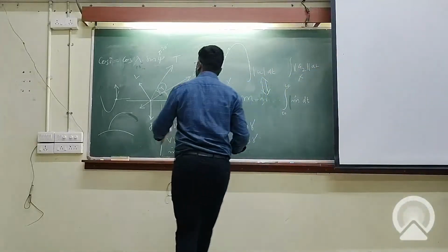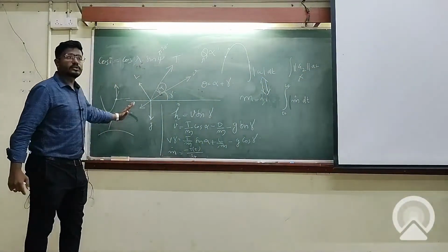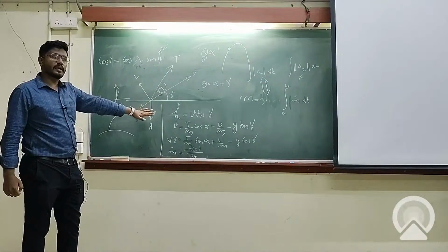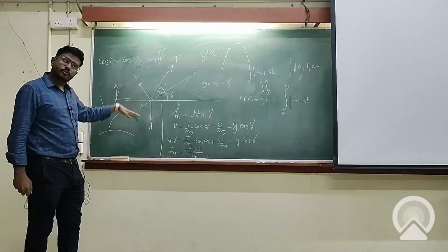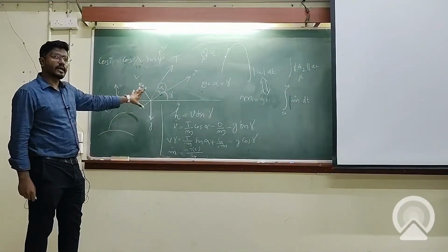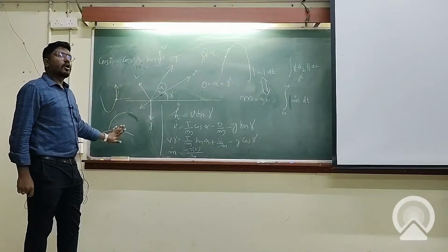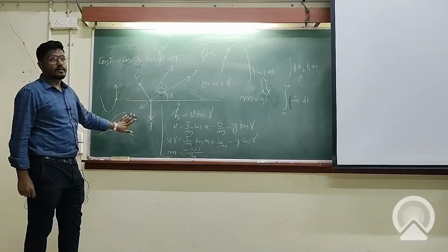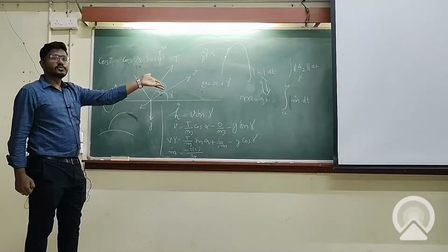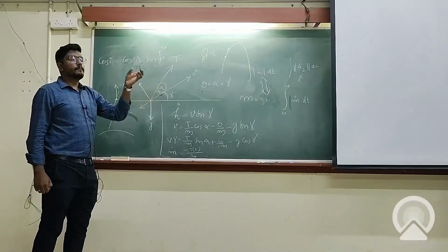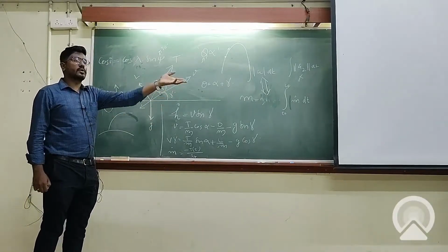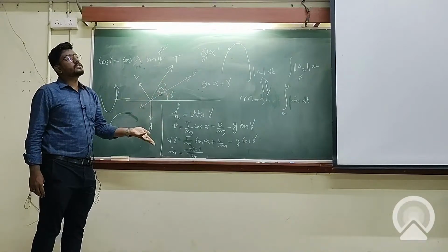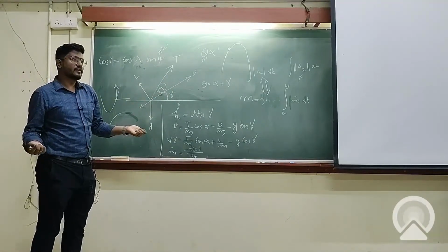See, basically, what are we doing? We are gaining altitude, we are gaining velocity, right? So your energy is spent for both these activities, gaining altitude and gaining velocity. Gaining altitude means you are firing against gravity. Gravity losses are there. You have to minimize the losses. So it is always better to fire along the velocity vector and we get altitude gain for free. Right?